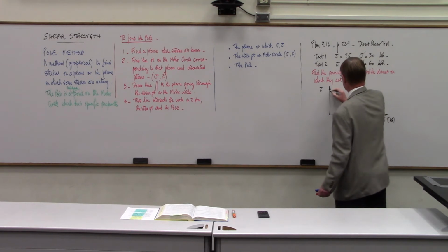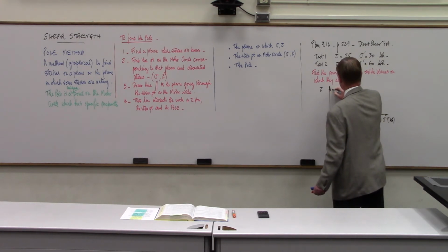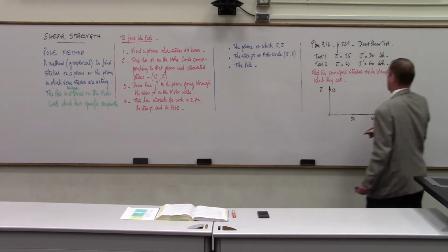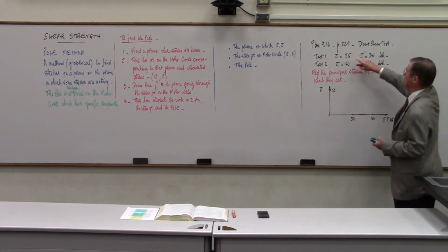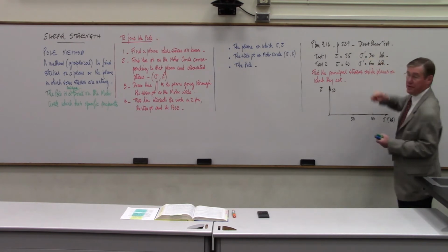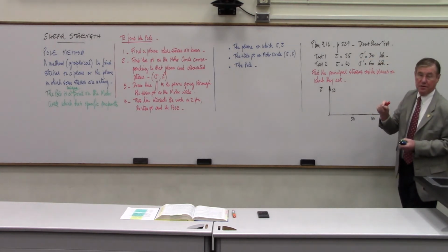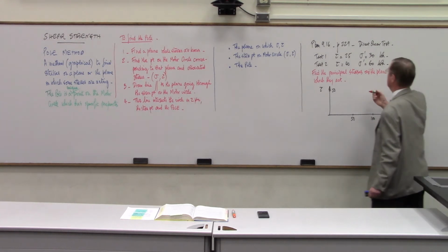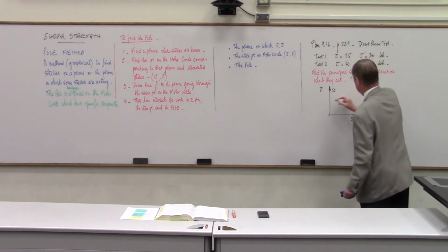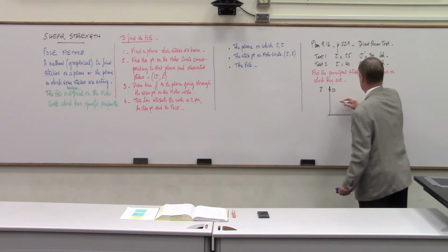And then I've got to have the same units here, so this is going to be 50 as well. And these were the shear stress and effective normal stress at failure for that particular direct shear test. So at failure, I had 25 and I had 30.